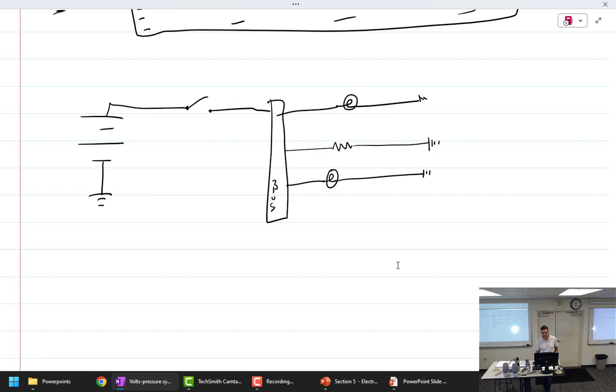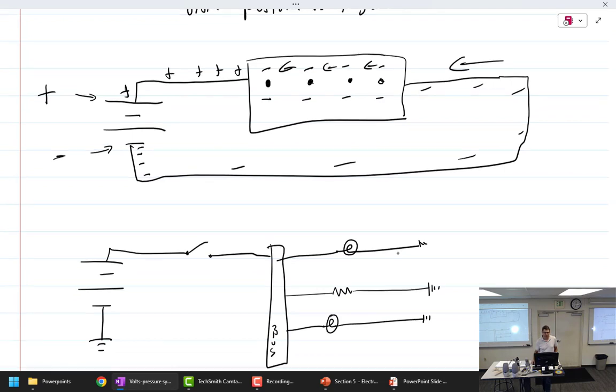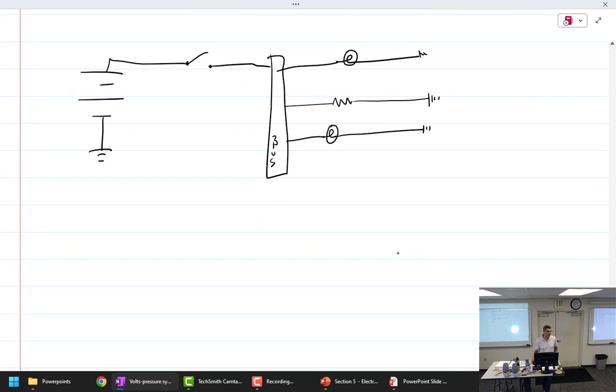But what I've drawn is a battery, and when you look at a schematic, it doesn't show the negative wire coming around and connecting to anything, because it's not wired that way on an airplane or a car. You take the negative side of the battery, and if you look at your car, your battery cable is about that long, and it goes from the battery down to a piece of metal on the chassis, and that's it. And then the positive wire is going to run out.